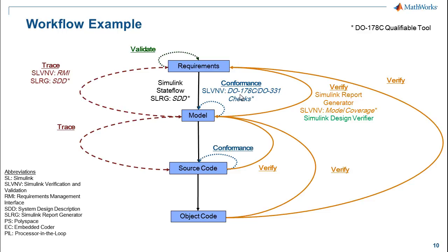Most of our customers have already figured out a way that they like to do that, and that's fine. My only suggestion specific for a workflow like this is whatever you have done, wrap that up inside a Simulink report generator template. The reason for that is so that when you're done executing all of these test cases, you also automatically get out a report that shows the results of all of those test cases. Because again, reporting is such a key aspect to a workflow like this. All right. So that's about executing and automating the execution of your test cases.